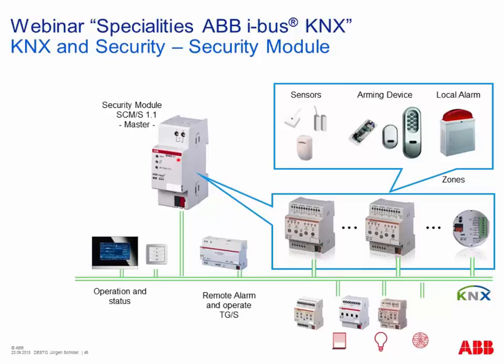And here we have the same. It works like our standard standalone intrusion alarm panel with the logic, internal set, external set, delayed setting. Additionally, we have an event log inside, which records the last 250 events. For example, when was the system set, time and date, or which sensor made an alarm, including the name of the sensor. Each of the sensors can get a name with up to 14 characters, and all these things are here stored inside the event log.